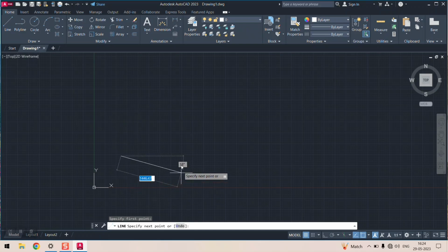So horizontal, the x-axis, is your 0, and if you are moving towards the y-axis, your angle will increase. The angle is moving in steps of 1 degree. It's not increasing 1.2, 1.3, 1.4 because precision was set to 0 decimal places. When we were changing the units, precision was automatically set to 0. So the angle will automatically increase in the format of 1 degree.